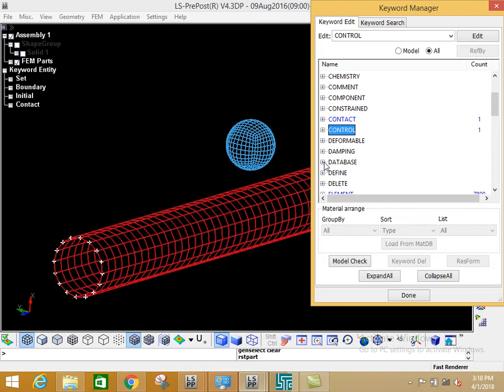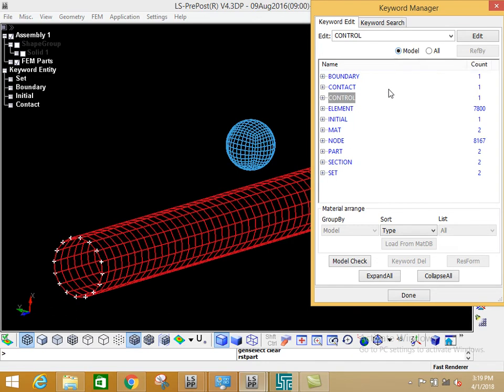So you have a question? Yes. Since we have so many steps, how do I check whether my step is correct? Okay, you complete everything, you save as K file, then you run in the LS DYNA manager. If there is a mistake, the solution cannot run. The software cannot show what I have input previously, like the termination with the details? You can check manually, one by one. It's not shown on one page.